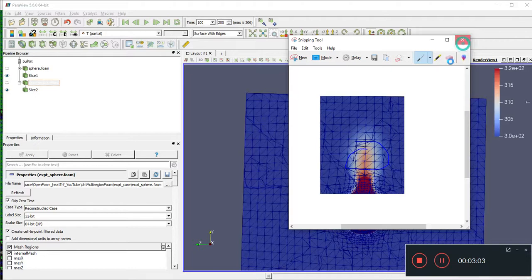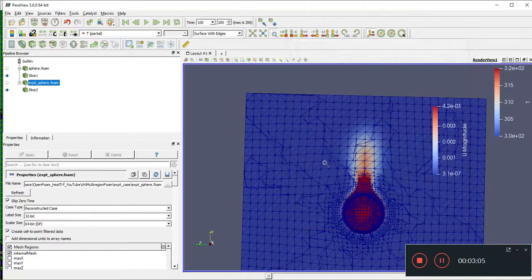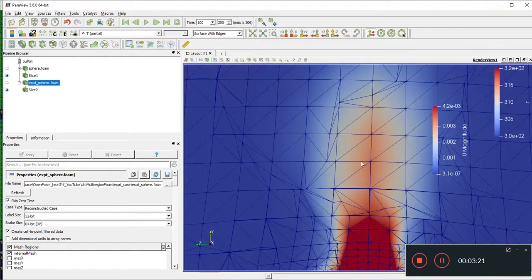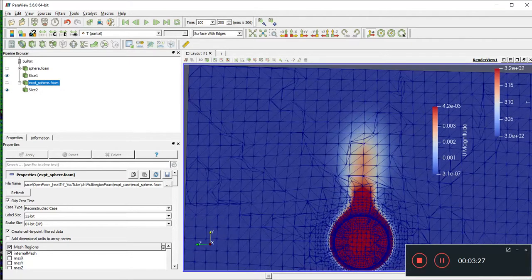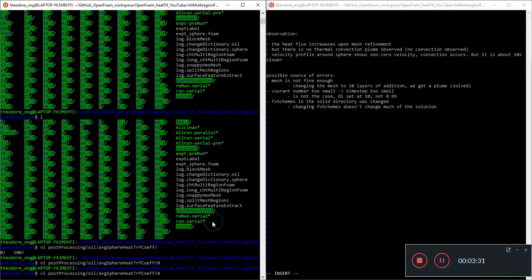Now I'd like to opt for the layer addition. Of course, that may increase the computational time a lot, but it does make for a very nice mesh and accurate results. For now we want accuracy, not speed yet. So you just want the most accurate mesh, and I'm going to go with that. Let's try a few options of remeshing this.